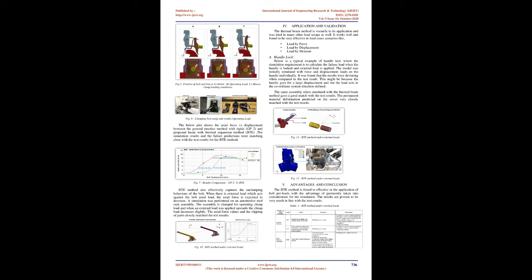C. Contact. Surface-to-surface sliding contacts are defined between the bolt, nut, and their connected parts. This makes sure that the area of the bolt head is effectively captured and the sliding effect, if any, is also simulated. Note that there is no contact defined between the bolt and nut as there is interference in CAD. The link between bolt and the nut is the beam element connected to the shells of bolt and nut, as explained in point 2 of section A. The cylindrical joint created between the bolt and nut ensures the relative movement between the two parts.